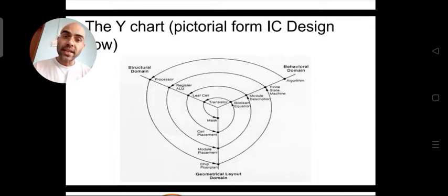Then in the next stage, to get the optimum design, the various blocks you have designed should be at optimal places, so that the parameters which you have already discussed are minimum. So then you do the chip floor planning. Chip floor planning means the broad level at which you decide which modules will be placed where, and which broad blocks will be placed in which regions. That is what we design, and then we keep moving on to the lower levels.